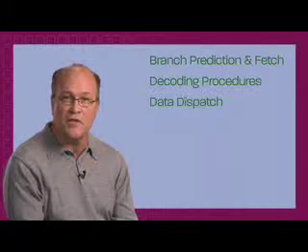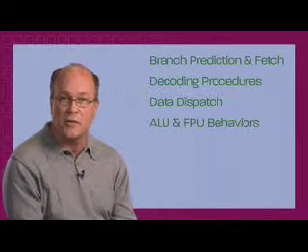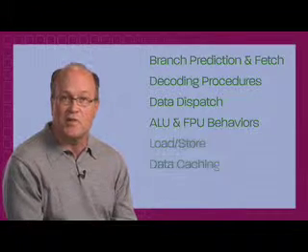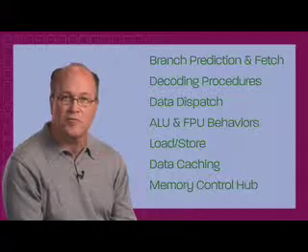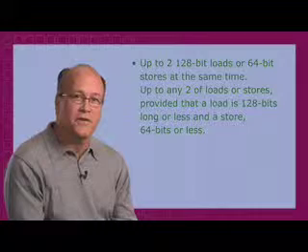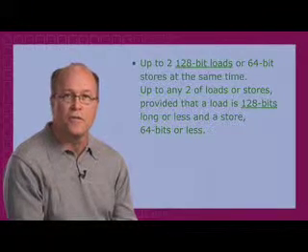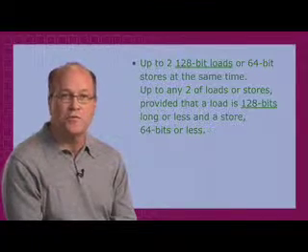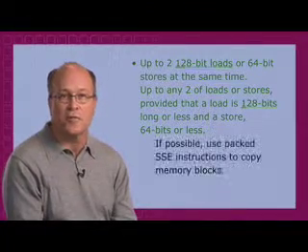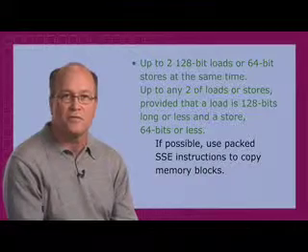The subjects we'll be covering after an overview of microarchitecture are branch prediction, decoding procedures, data dispatch, ALU and FPU behaviors. We'll examine load store and data caching and finish up with the operation of the memory control hub. Throughout this presentation, we'll clarify differences in the new processor from previous generation AMD Opteron processors, pointing out new characteristics and underlining appropriate optimization techniques.